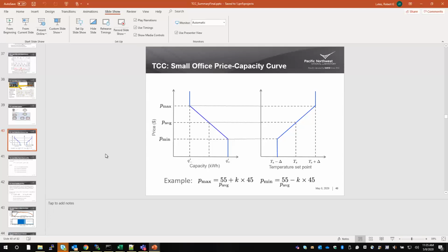What BACnet doesn't have is the understanding of the market service and how to adequately participate in the market with so many different devices. BACnet is just a communication protocol. Basically, it's just a way to package the information from the building automation system in a standardized way that different entities and different devices and things like Voltron can utilize that data, for interoperability, really.